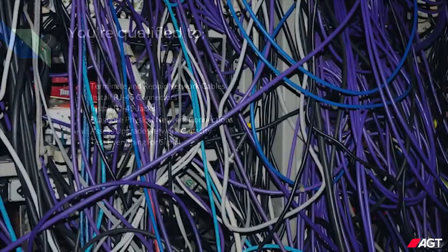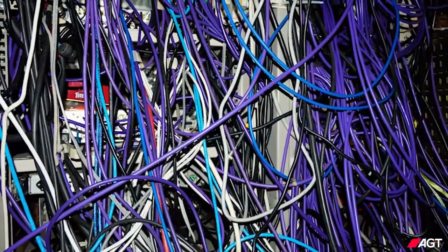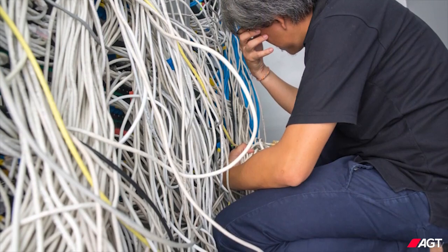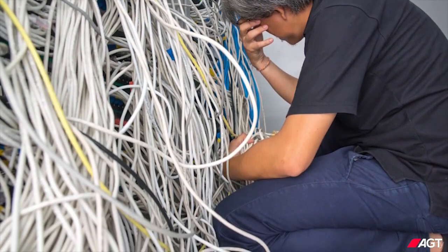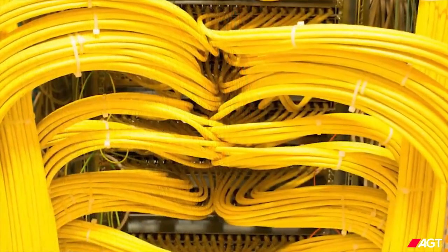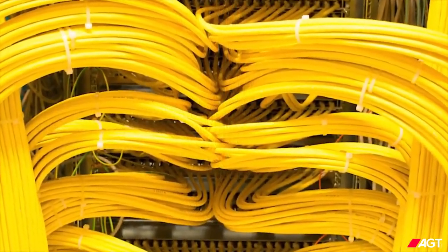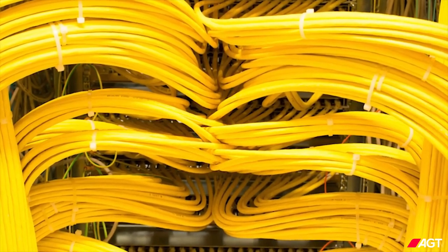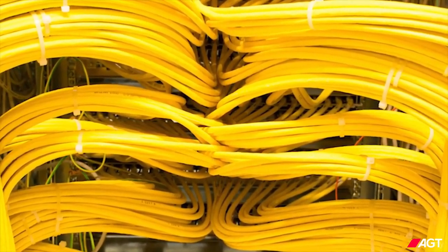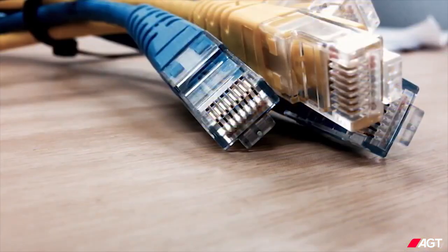That reminds me, neatness counts, especially when you're working for a client. You want your work to be easily understood by the next technician after you. You don't want them to be telling your old client that you did a messy job. So when running multiple cables, always use zip ties and keep your cables organized. If you need to, label them too. And again, it should always be one continuous cable from point A to point B. So that's really all I have to say about cabling.